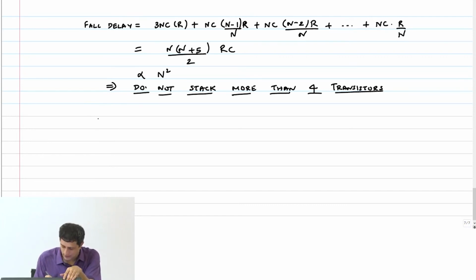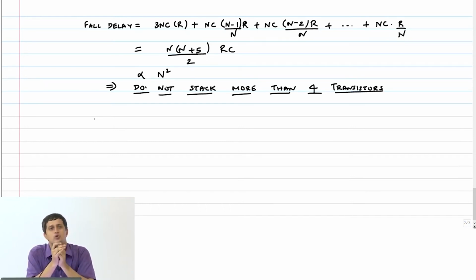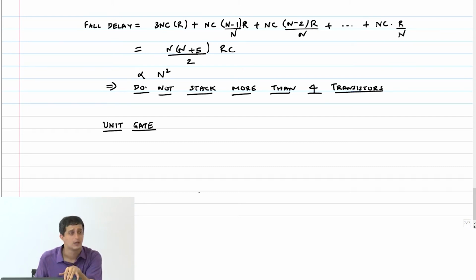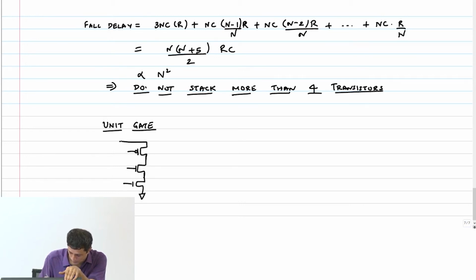So now let's proceed with another interesting thing, because it's not possible for me to achieve the timing that I want on the circuit with just these unit gates. When I say a unit gate, let me define what I mean. So for example, a NAND 2 with sizes 2, 2, 2 and 2.